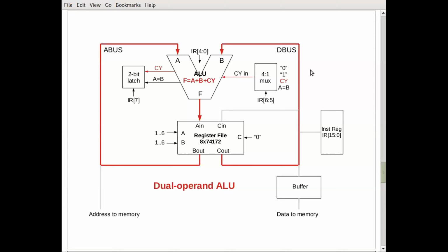And the result goes back in and replaces that first register. Actually, it doesn't have to. Sorry, I'm thinking ahead to the next generation. I'll come back to that in a moment. But the third register is output and stored in the register file. So that right there is the add with carry. And of course, to add without carry, you simply select that the carry is 0 instead of the carry input to this part of the board.